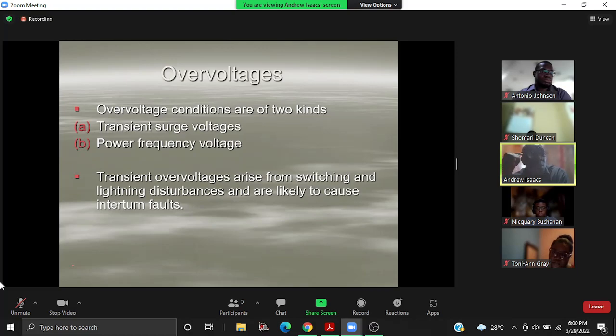So for those who may have to consider the whole operation of taps, for whatever reason they may need to consider it, they would have to appreciate that one of the benefits of the tap changers is, well, it has already been said, to regulate the voltage, keep the voltage within spec. So I want to keep it within that 5%.